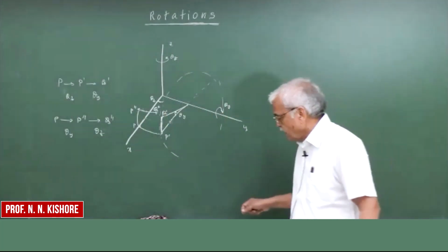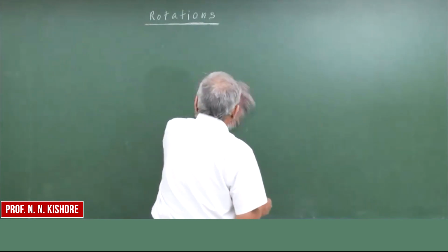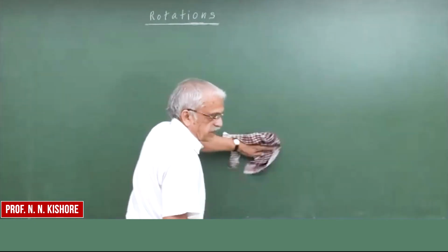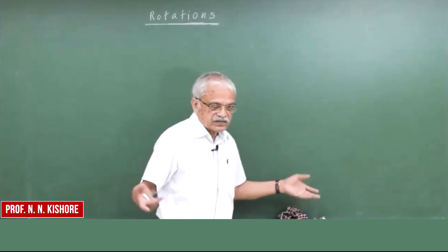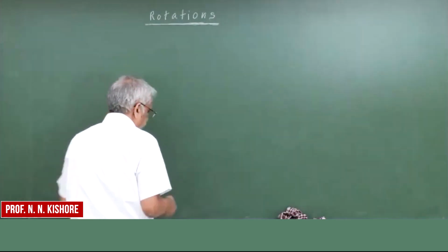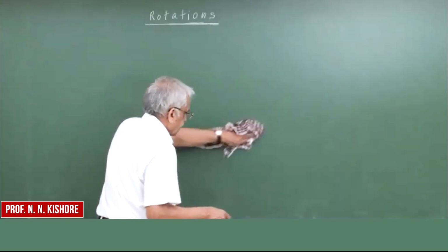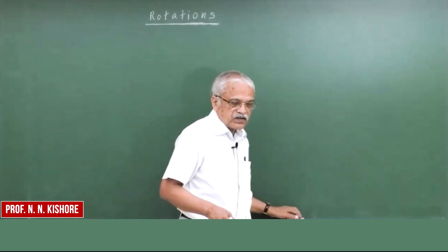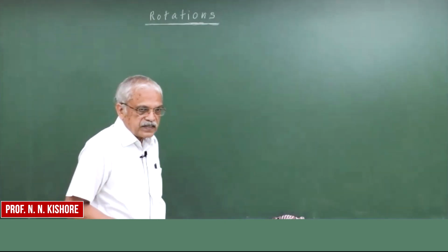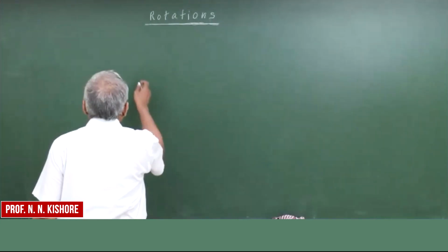I hope you had that picture in mind, and so I'm going slowly. First, I demonstrated by a simple thing, using 90-degree rotation about the Z and Y axes, that rotations do not commute. And also here, with these two slides, I have explained that finite rotations are not commutative, but when they are small, the discrepancy tends to 0. So let's try to do it.